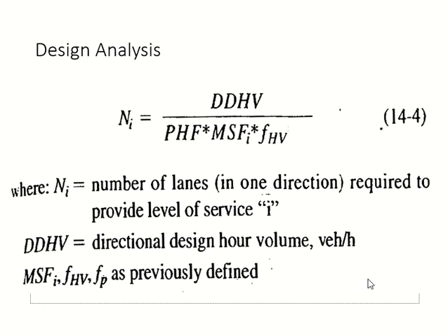The drivers are enjoying, yes, but they shouldn't. They are human beings, right? Human beings are here for tests and trials. They are not here to enjoy. So they must have delay. They might get stuck in traffic jam, and so on and so forth. This is part of life. Clear? The point is, aiming for level of service A, even in the peak hour, even in the design future volume, will be too expensive. It will be an impractical design.